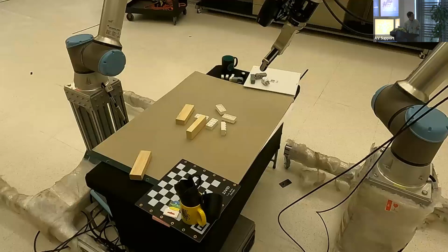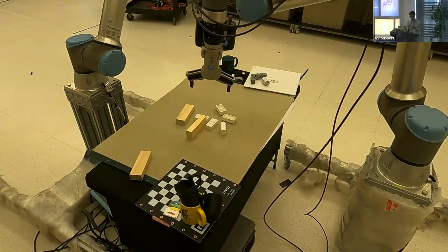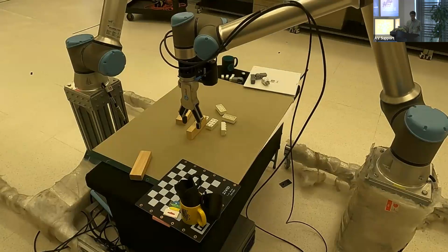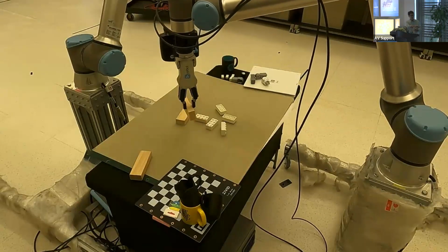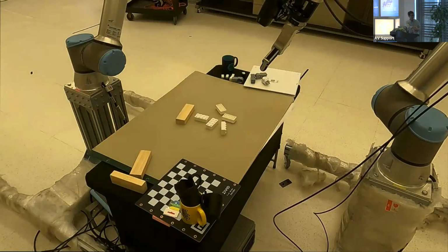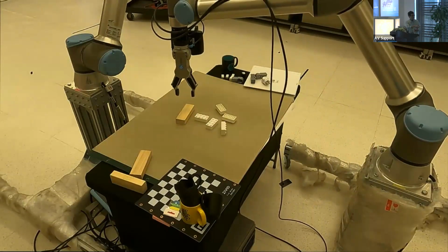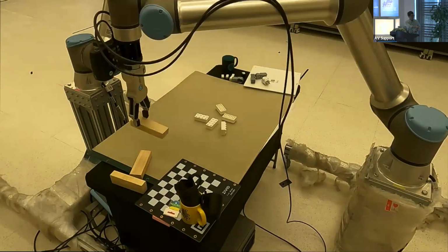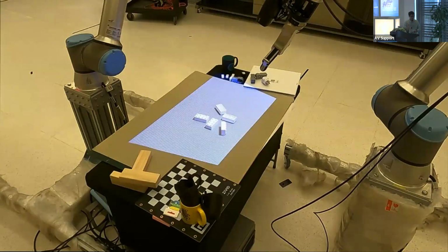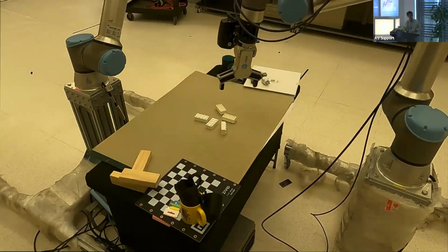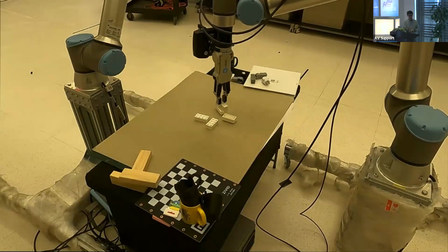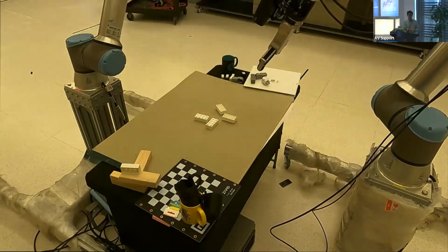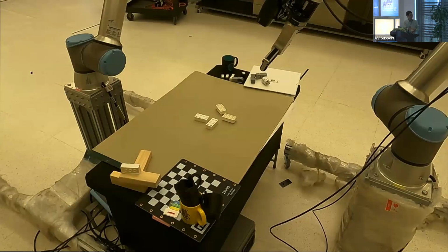So if you actually do the experiment, what would happen is if we have a static object on the table, the robot has not much issue with identifying the object itself and its location, extending the arm and doing the pickup. It's not a very difficult task. But while the robot is sensing, identifying the object on the table and trying to extend the arm, if somebody slightly pushes one of the objects on the table, then most likely the robot is not able to pick up anything. So one of the challenges we are trying to solve is that the camera system is great, but there are some challenges with the frequency of the sensing part.